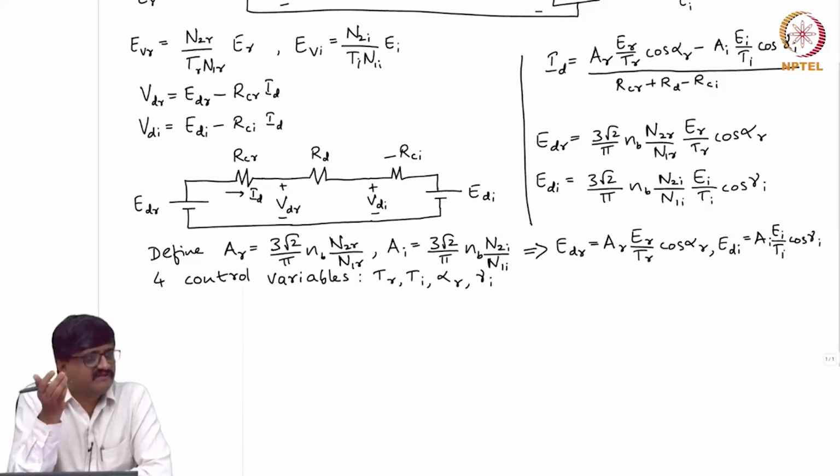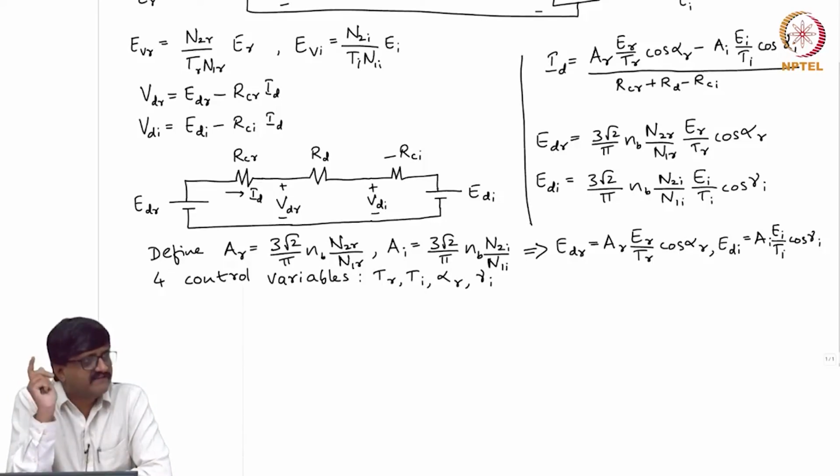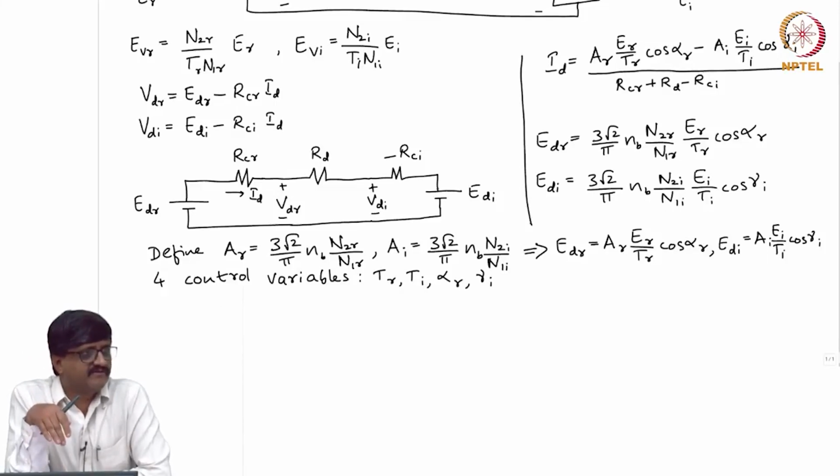But if you look at a thyristor, how many times in a second does it switch on and switch off? Take a 6 pulse line commutated converter, take any thyristor: 50 times. There are many other faster switches in fact. So, the slow power electronic switch that we are considering here is itself switching on and off 50 times a second.